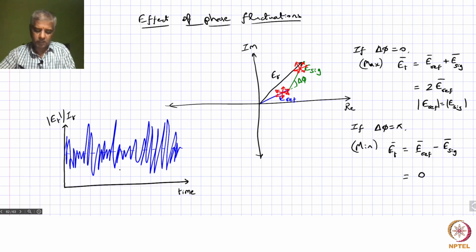So how do you now extract the real intensity that you have, the signal intensity, or the beating because of the signal intensity, and then how do you extract the corresponding phase? That is actually the typical challenge as far as a phase modulated sensor is concerned, as far as this Michelson interferometer based phase modulation sensor is concerned.